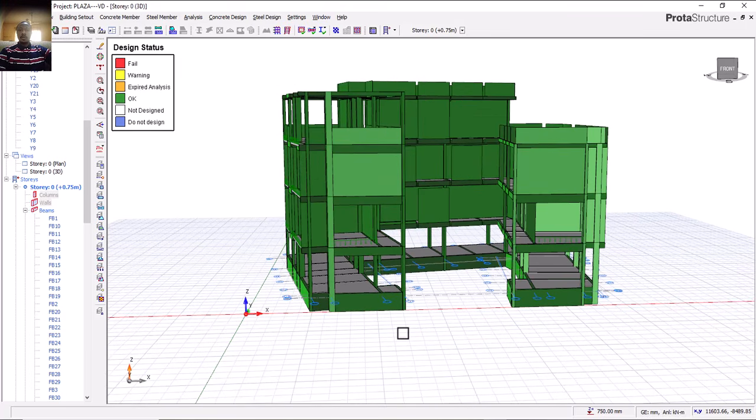So this is how you go about your beam raft design. Though there is another part to this beam raft design in a situation whereby your structural pressure is more than the soil pressure. How do you go about it? That's another phase. Is that okay?